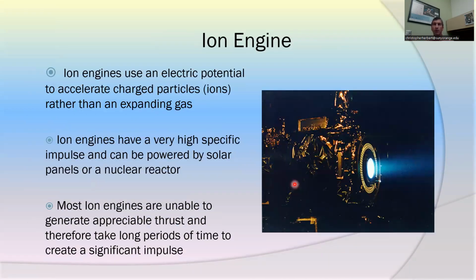So the general thought is this: we boost these rockets into some orbit, and then we use the ion engines to get to a higher orbit, or for the case of low Earth orbits, for instance, the Starlink satellites have these little ion engines on them. We're thinking about putting ion engines on the Gateway space station to the moon when that is launched.